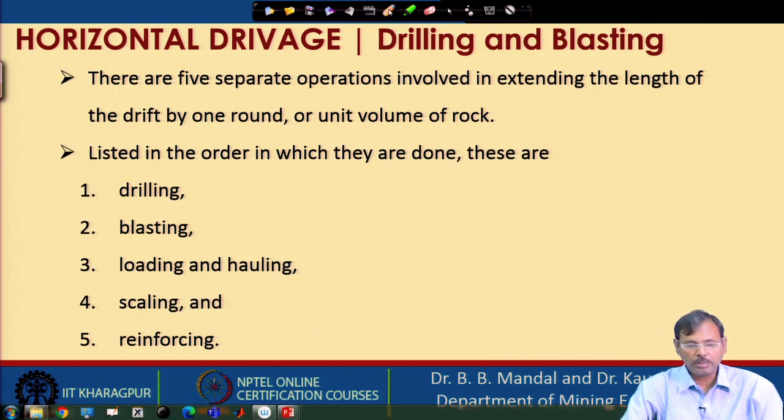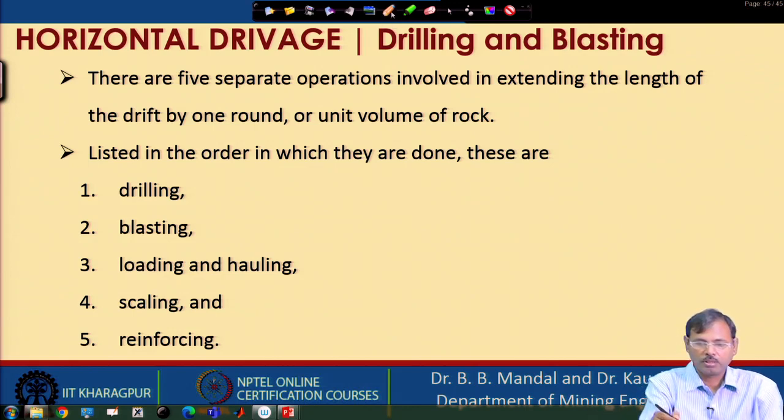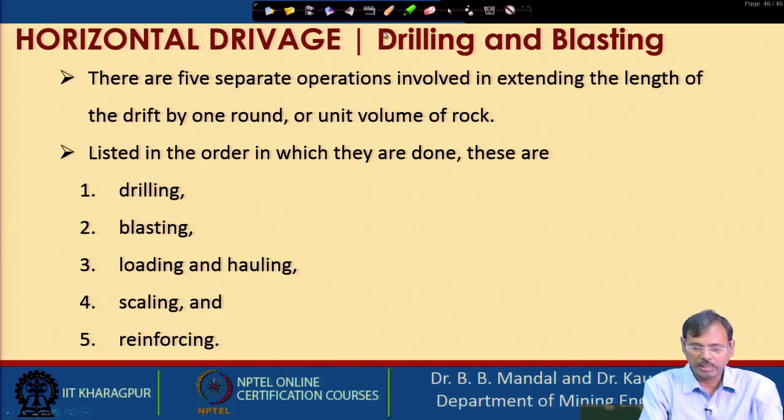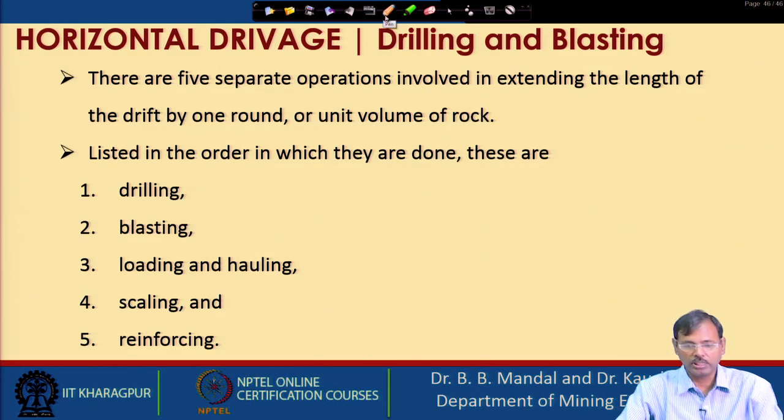So, in a nutshell, we can consider the discrete method of horizontal drivage excavation consists of drilling, blasting, loading and hauling, scaling, reinforcing. Okay. And along with that, other auxiliary works are also there.